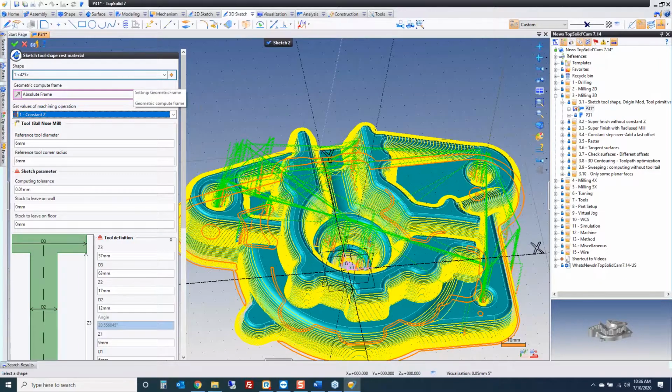Okay? That creates the curve, and then from there, you click OK, you save the curve. You can use those in any of the 3D toolpath machining strategies. So just a nice little toolpath, or nice little feature to help find the areas that still need to be machined.